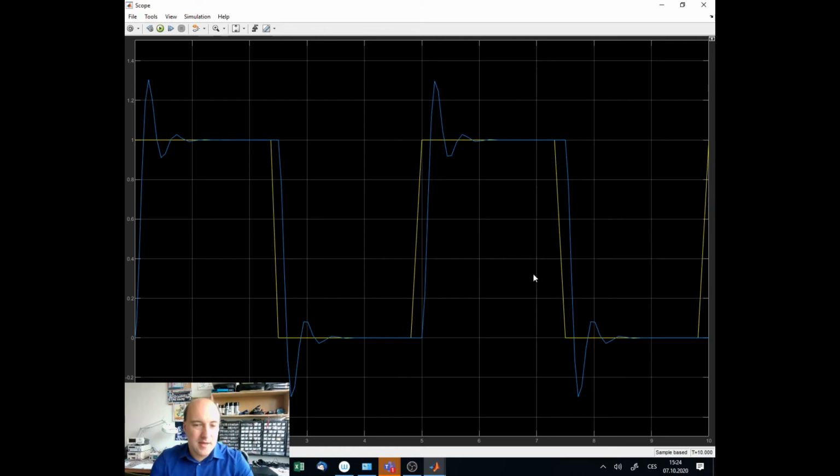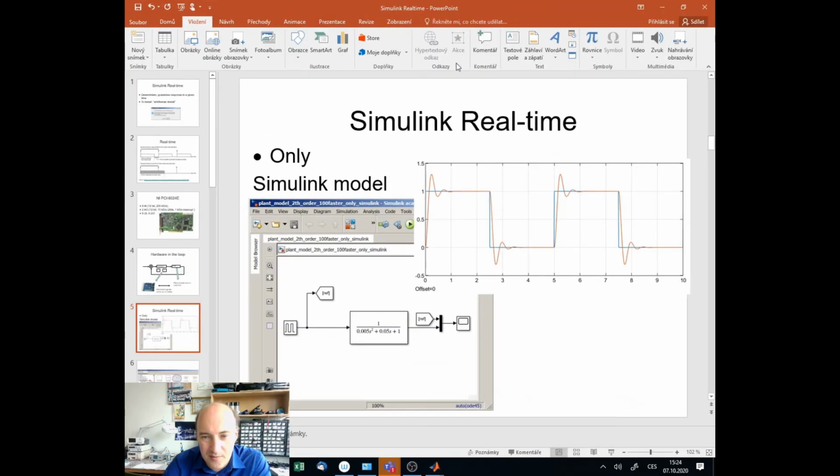And since I did not set any setting for the minimal time step, now you can see that this time step is quite large, and that the signal here is not very vertical. If you have a small time step, it will look like this: 0 on the input, and then ideally in a very short time, infinite time here, then it will jump to 1.